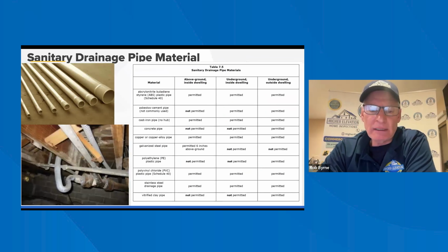And you can see down in the basement, obviously you have that cast iron drain being supported by a strap. Then you have another one coming off that's galvanized. So those are the things that you would call out and look at. Those are old types of drains.